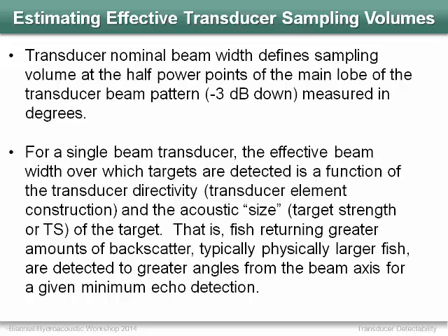We talk about our transducer beam widths, and typically transducer beam widths are defined at the half power point, the point at which you get to half amplitude energy as you move down that beam pattern. And typically if you look at beam plots with your calibration, your 15-degree transducer may spec as a 14.1 or a 15.2. They're consistently built with the elements, but there's always a little bit of variation even within a lot or so on.